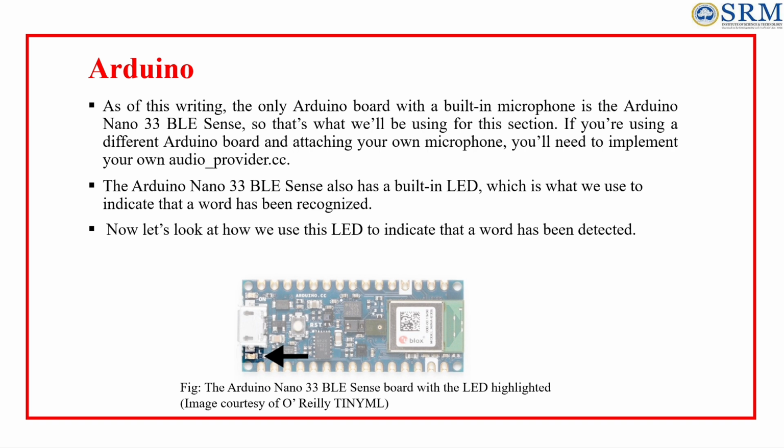Capturing audio. The Nano 33 BLE Sense has an onboard microphone that provides the audio input. If you are using a different Arduino board, you will need to attach an external microphone and implement your own audio_provider.cc file to handle the input. And on the Arduino, we use the LED to indicate that a word has been detected.